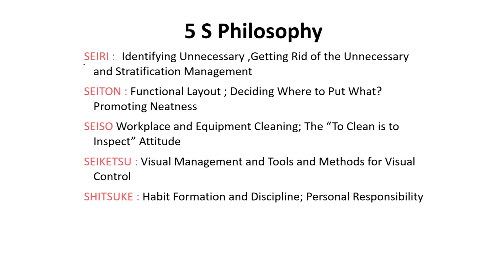The first S is Seiri: identify unnecessary items which are not required and get rid of these dead items, non moving items, and whatever is left you arrange, stratify and classify in a nice manner. Third is Seiton. You should have a functional layout where each item is kept at a place, a place for everything and everything at its place.